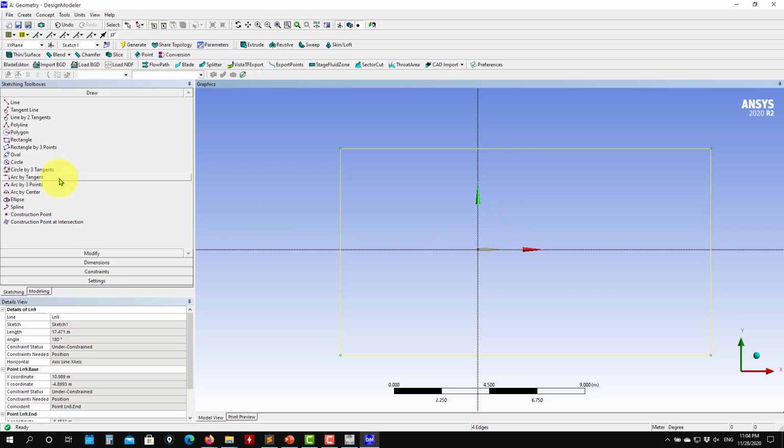So why do we need such a big box? Because here you're going to have a pressure evolution, and also a velocity gradient. So we don't want strong gradients close to the boundary, because that can affect the stability of the solution. So you need to put that far away in such a way that you don't have strong gradients.